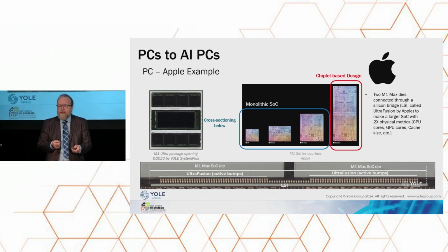When you reach the Pro series, Apple has taken basically a single M core and used an interposer to duplicate that for purposes of being able to fit within a particular reticle size, and at the same time providing more resource and better yields.